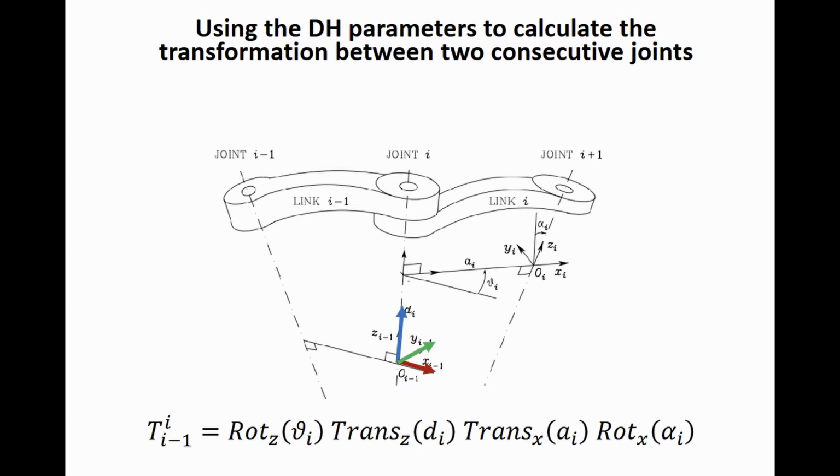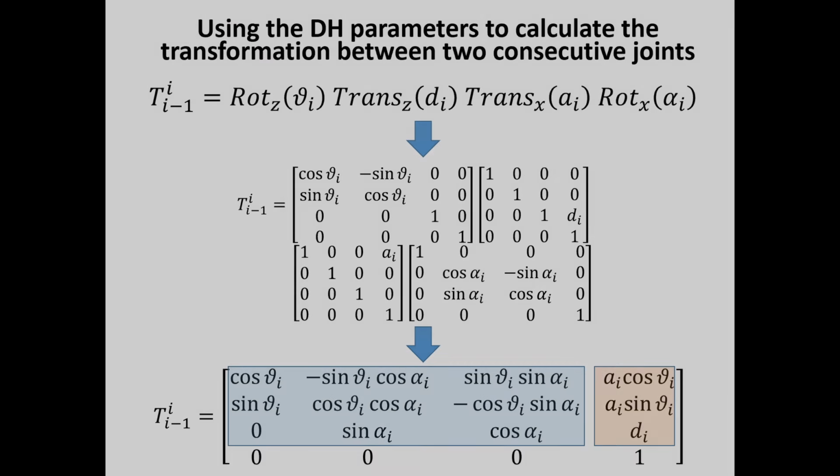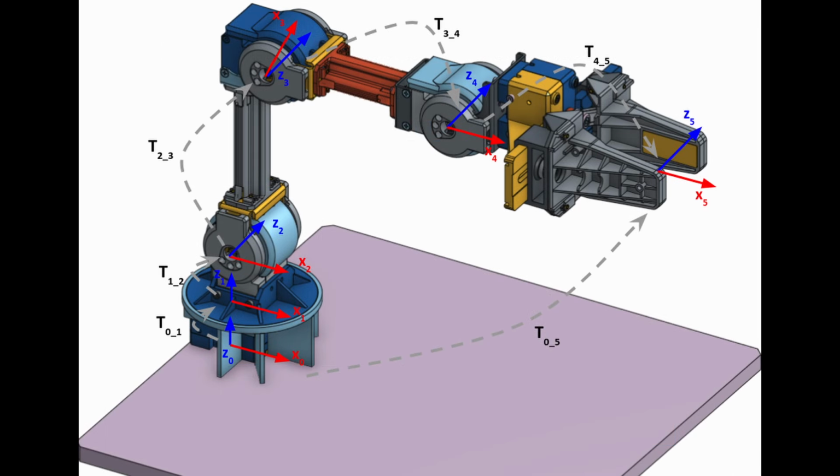are selected for each joint along the kinematic chain, allowing us to get homogeneous transformation matrices from each joint to the next. By multiplying all these matrices together, we get a single transformation matrix that takes us from the base frame to the end effector frame. Substituting in a set of joint angles into this final matrix gives the position of the end effector with respect to the base frame, thereby solving the forward kinematics.